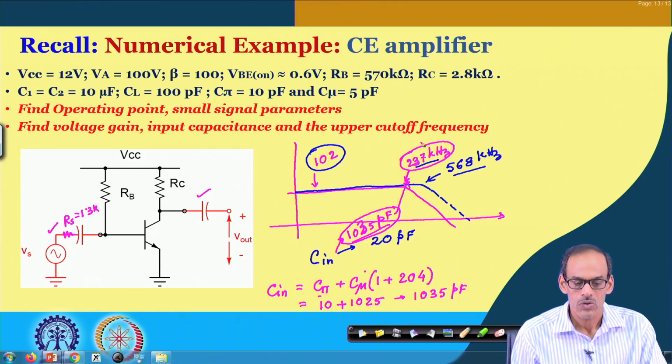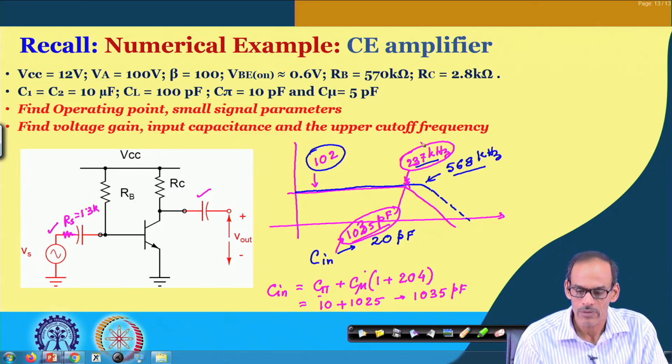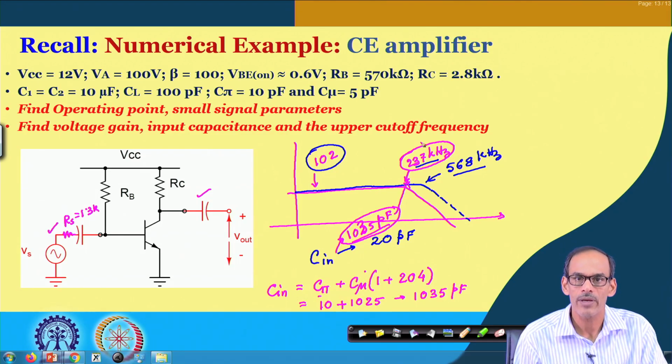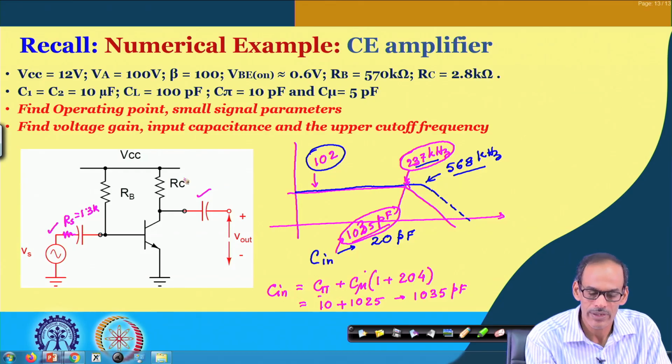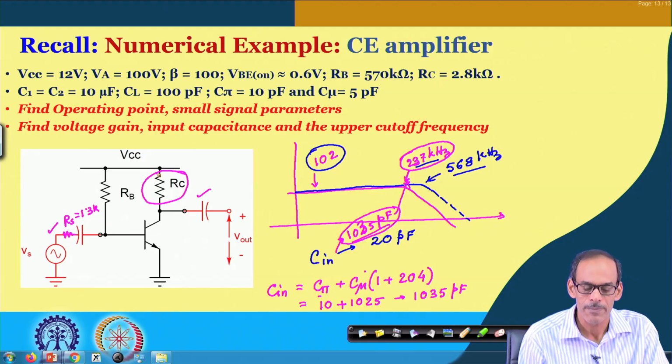Okay. So far what we have discussed is the advantage of the cascode amplifier with respect to the standard CE amplifier, namely that if we are retaining the passive elements for both cases, then gain wise we do not get much advantage.